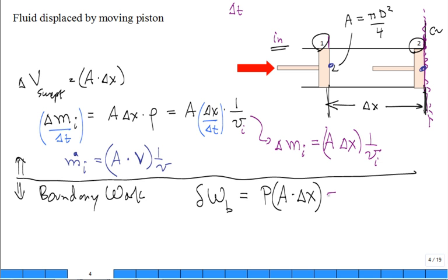So this is also equal to P times v times how much mass was swept in. So it's that inlet pressure times the inlet specific volume times the amount of mass that's swept in. That's that boundary work. I know that equation's new, but can you see why I wanted to write it that way? I get a natural Pv term. What is the definition of enthalpy?